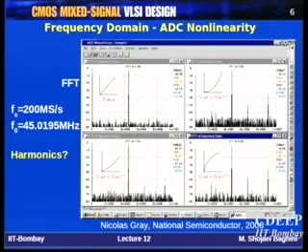It shows you the density of power for every frequency bin, like a power spectral density. This is your power axis and this is your frequency axis. Because it is power density, the effective power has been divided by the number of frequency bins. That is the reason you will get less SNR.